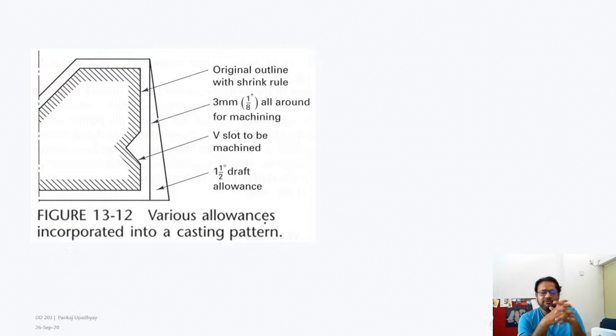It's okay, 1.5 degrees is okay, but for a good sand casting setup, especially a sand casting setup, around 3 to 5 degrees is what is sought after. Especially if it is a very flat and very long perpendicular surface, typically you should go for something around 3.5 to 4 degrees of draft angle. These are thumb rules, and they come from the experience of the manufacturers.